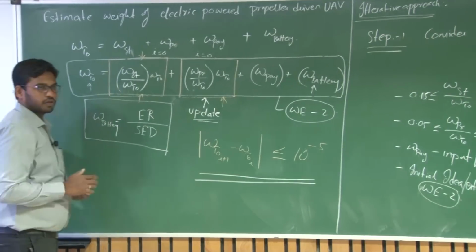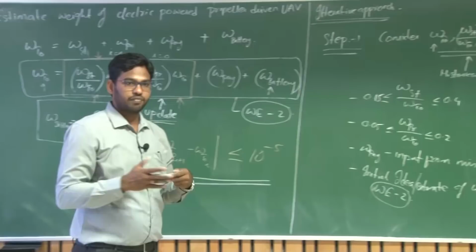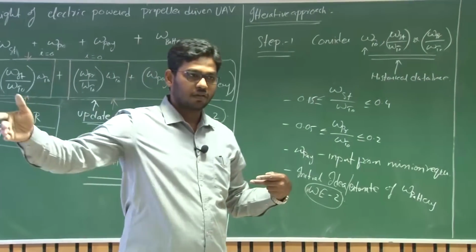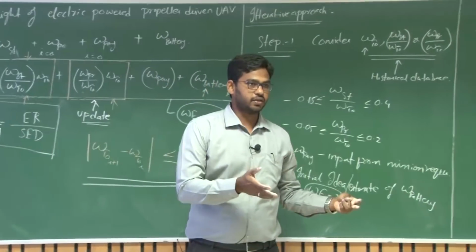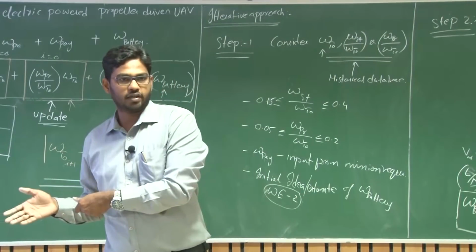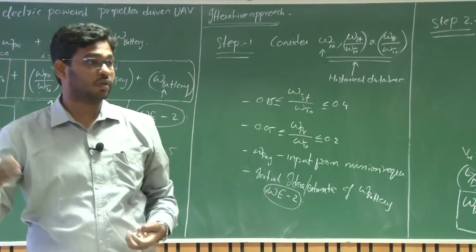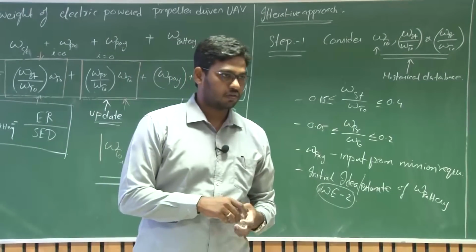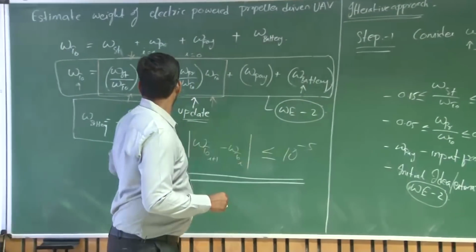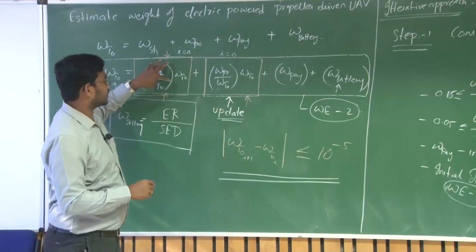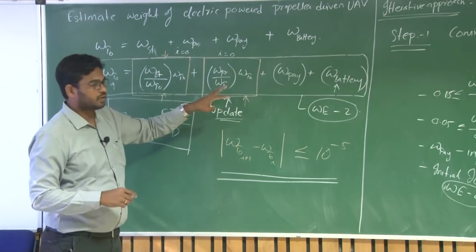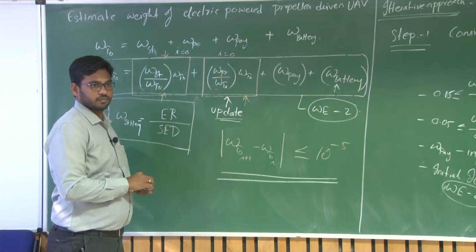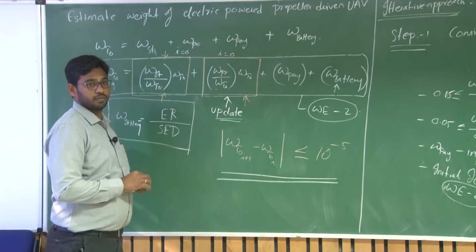Similarly, whatever structure you are going to design will have a factor of safety. The aircraft or UAV that is designed to carry 3 kgs will not change for 2.5 kg. The structure may not change significantly for 2.5 kgs, right? So you need to consider a higher factor of safety so that this iterative process, or the rounds of iteration, can be minimized.